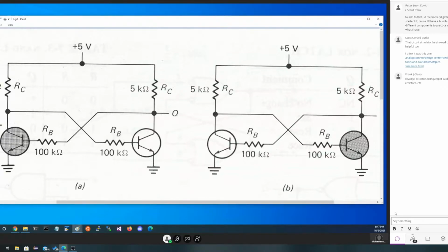0 volts. And if this guy is turned on, what'll be right here? Robert? Also 0 volts. Okay, but if there's 0 volts there, and that's tied through this wire to the base of the other guy, that means all of this 5 volts had to drop across the resistor. None of it ever made it to the base. Correct? Am I correct in saying that? Yeah, give me a green circle for correct there. Okay.